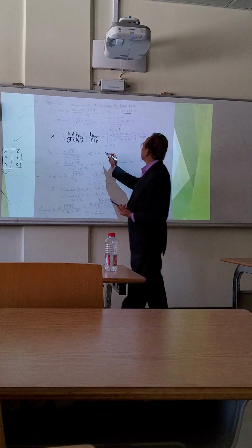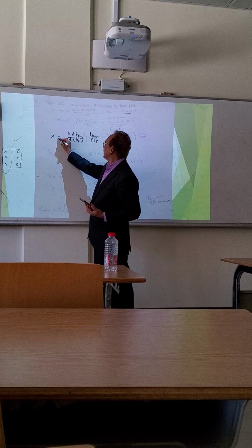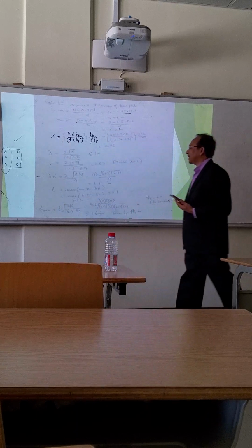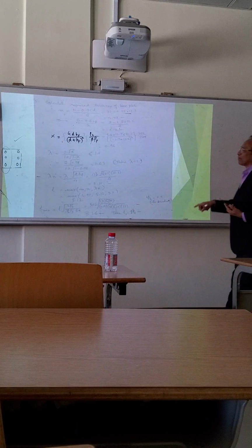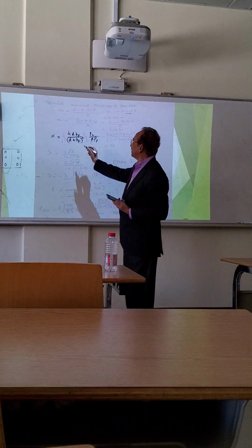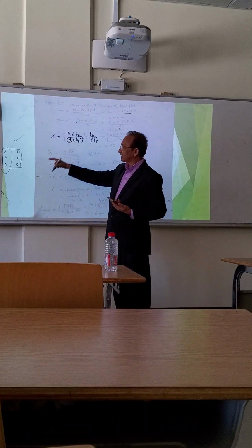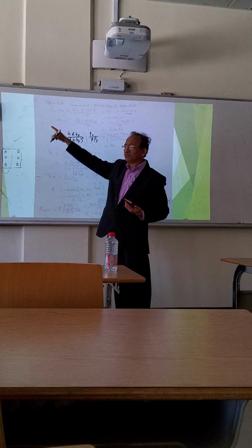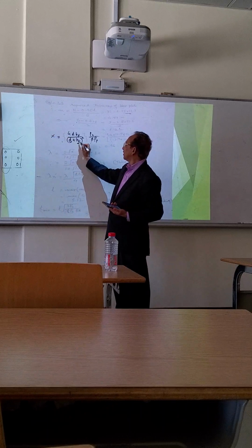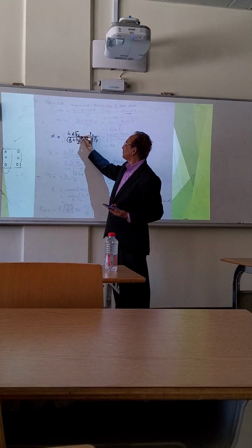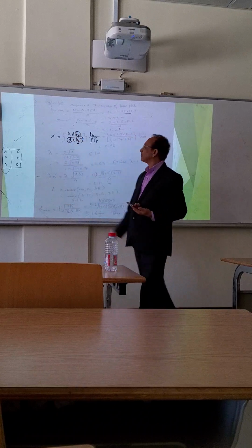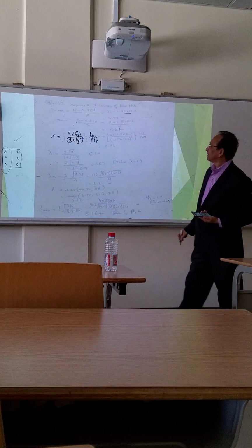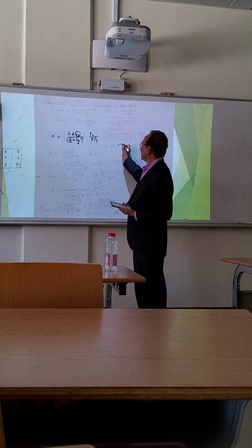So this x is a number which will be helpful in finalizing your value for n dash. Now, what is this d? D is coming from your column section, bf also from the column, from the data sheet. So when you substitute these values, you find x equal to 0.96.